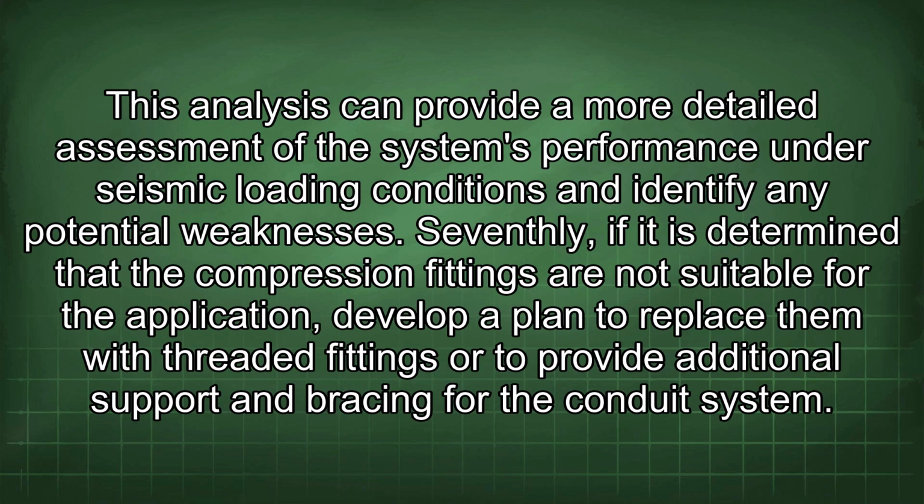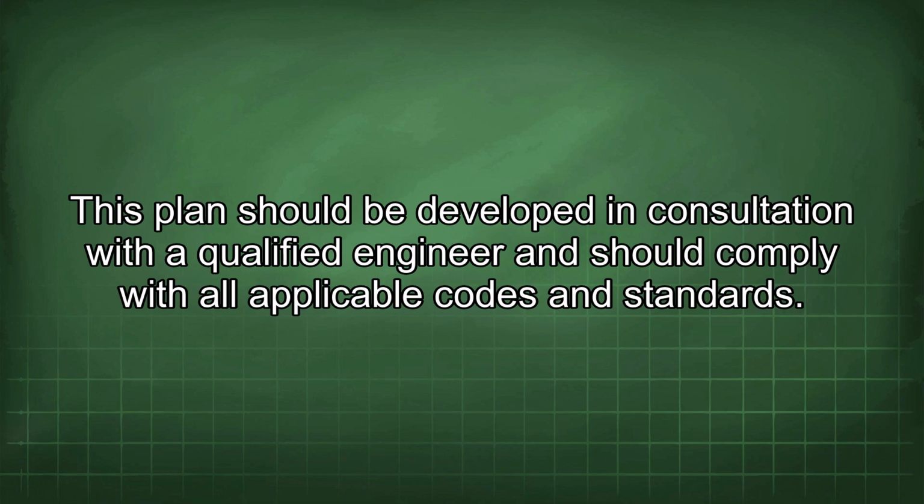weaknesses. Seventhly, if it is determined that the compression fittings are not suitable for the application, develop a plan to replace them with threaded fittings or to provide additional support and bracing for the conduit system. This plan should be developed in consultation with a qualified engineer and should comply with all applicable codes and standards.